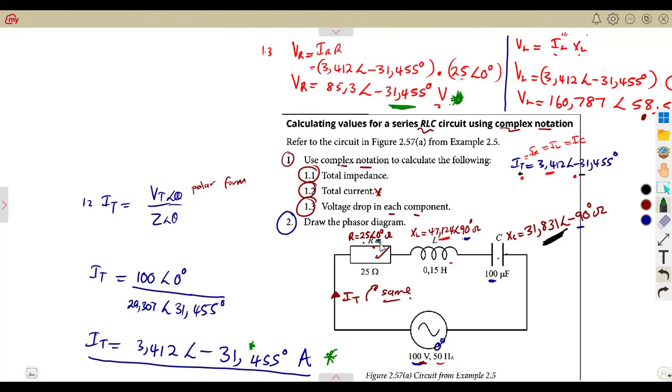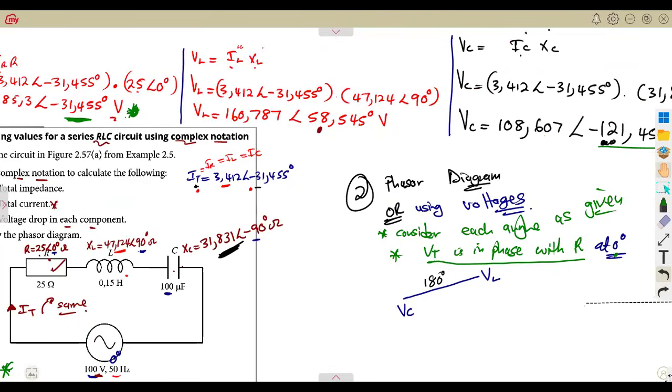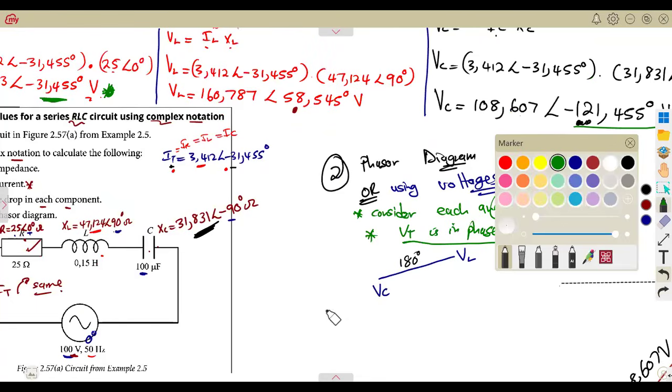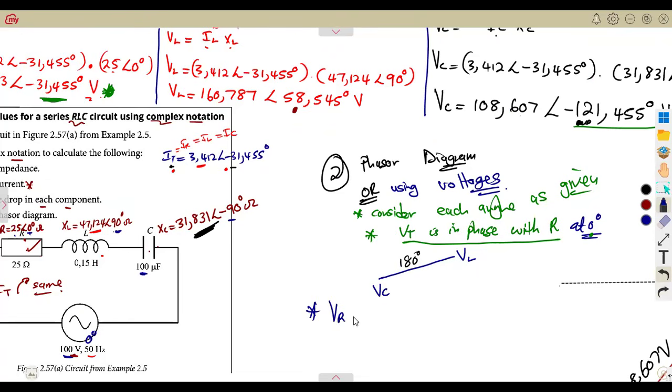Like what we had on the resistance, the angle on the resistance and the angle on the VT. So we are going to notice in every situation when it is like this, VR is in phase with what? The total current, which is IR, because remember, in series, IR is equal to IT, which is that total current. So instead of writing IR, we're just going to write IT, so that we're not going to have a problem. But that IT there is our current across the resistor.